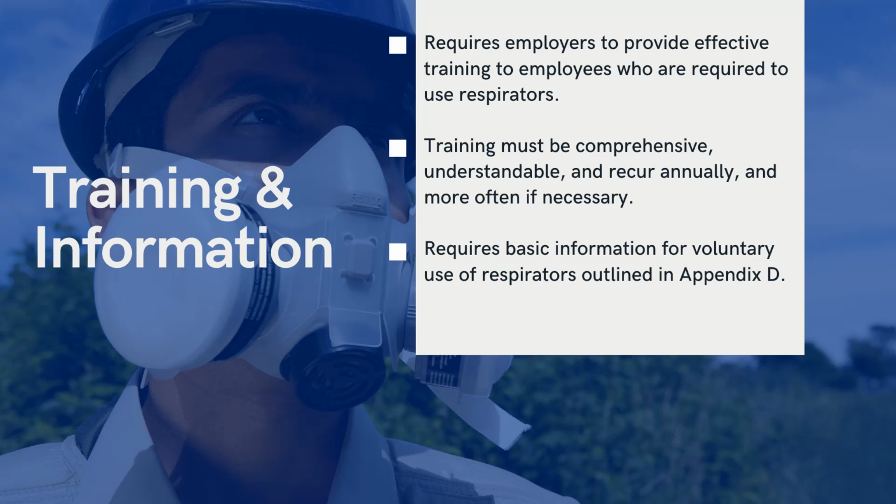Qualitative fit testing uses a method of testing that utilizes the wearer's reaction to a substance to test the fit of a respirator mask. Qualitative methods can be performed by isoamyl acetate, saccharin solution aerosol, Bitrex, and irritant smoke. These methods should only be used for fit testing negative pressure air purifying respirators that must achieve a fit factor of 100 or less.